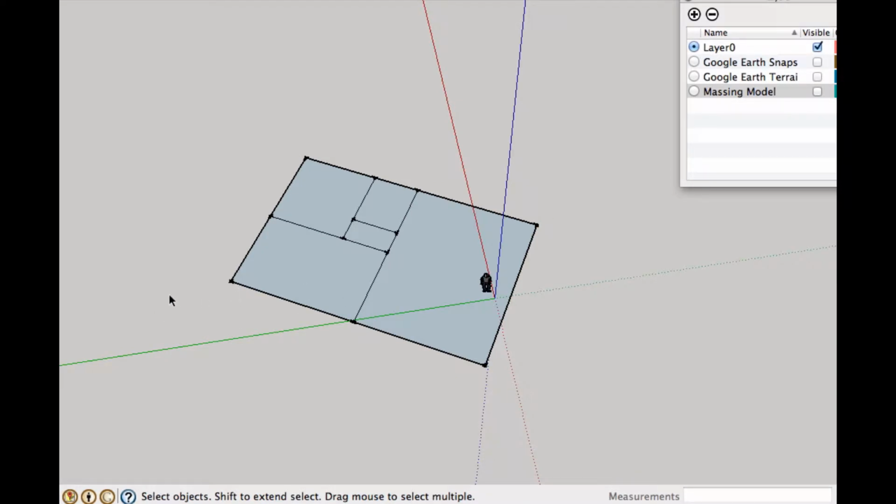So what if you did this? Now here's that thing where SketchUp wants to make the rectangle along the cardinal lines. So that's okay, we'll go with that right now. Now, the cool thing is, because this floor plan is in a group, I'm working outside the group, so this rectangle I've made actually isn't going to directly attach to any of the geometry that I've created inside that group.